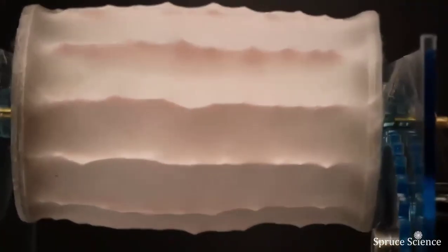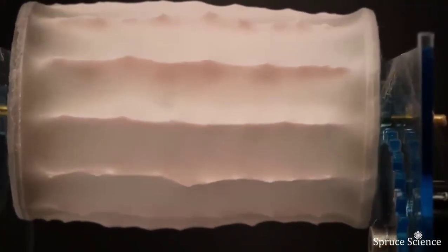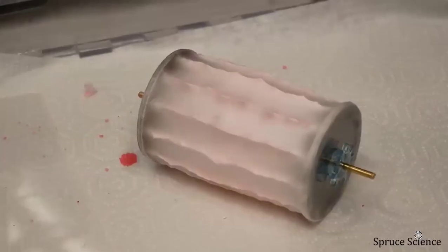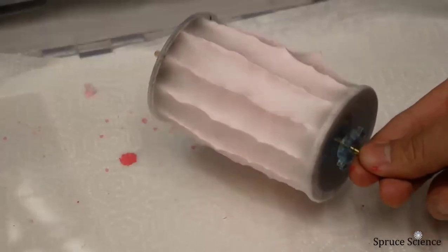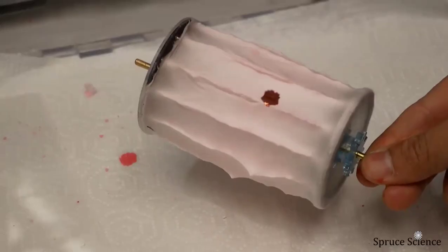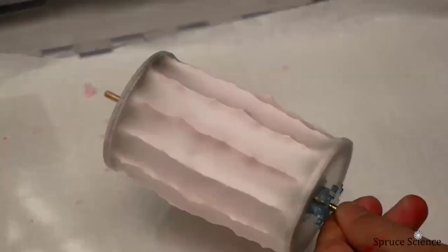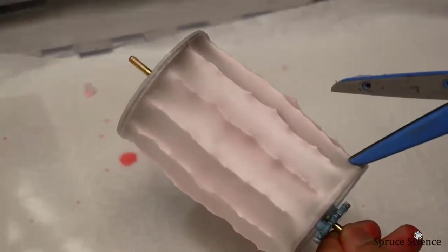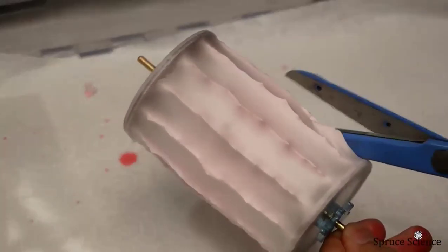Everything was going smoothly during the process, but once we turned off the high voltage power supply, a droplet formed at the tip of the needle. As it dripped down onto the fiber, it created a hole in the mat. It's important to be mindful of these potential issues and to have a plan in place to address them.